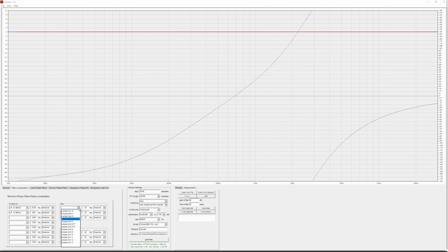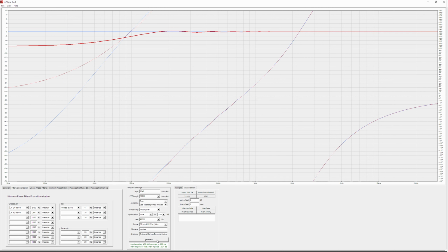And now let's assume we also had this box correction at 41. Then even with 2048 taps, I think, as you will see, with low frequencies, lower taps are horrible. It will have problems. It's possible to optimize this better, but it will never be perfectly matching the phase and the frequency response together. If I don't optimize the frequency response, it will be a better phase response, at least here. But look at what happened to the frequency. 6.5 dB drop in the low frequency volumes.